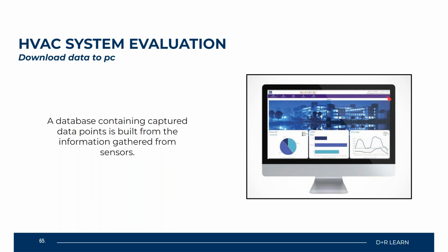We can sit right here after we've installed all those sensors and look at all of that information on this screen. And typically this is done by a building automation engineer or technician that is assigned to that facility to observe its energy usage and also its HVAC operation. So your BAS system is very, very important in your commercial sites, and it makes life a whole lot easier.